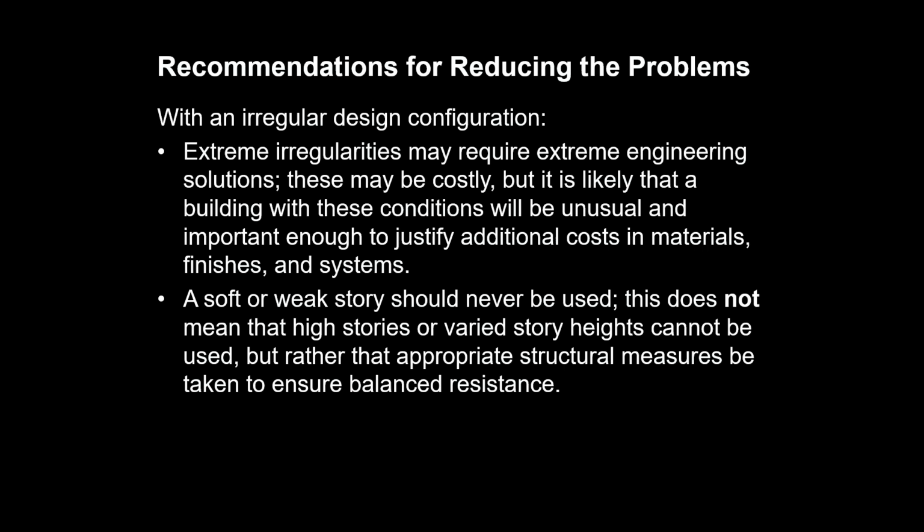Extreme irregularities may require extreme engineering solutions, which may be costly. A soft or weak story, and that can't be overemphasized, should never be used. This does not mean that high stories or varied story heights cannot be used, but rather that appropriate structural measures be taken to ensure balanced resistance.